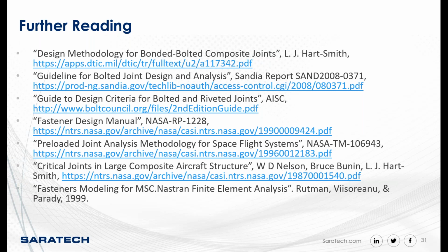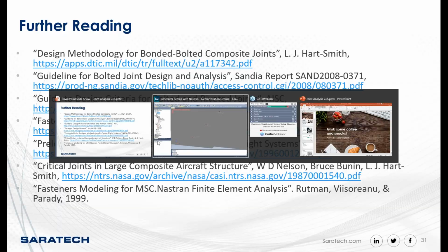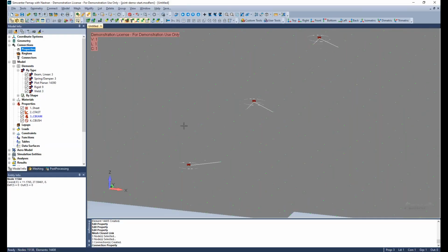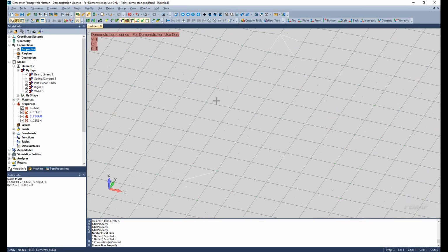And in the CFAST elements, why did we not choose all the plate elements connected to the fastener location? Good question. Let's talk about that. I appreciate that question. So we could do that. Remember, we're connecting patches together, and in this case, I defined the patches as being a pair of elements. So only one element per patch.